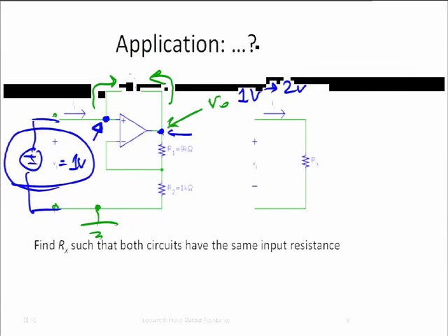Well, now that we have argued that it doesn't matter what the value of RF is, we can recognize the remaining circuit as, what is this? No, it's not just a voltage divider, right? There is an operational amplifier there. Somebody said it. This is a non-inverting amplifier, right? The gain of this thing is what? It's actually the ratio of these two resistors plus 1, it's 10. And if you don't remember that, well, look at your homework, look at your book and so on.